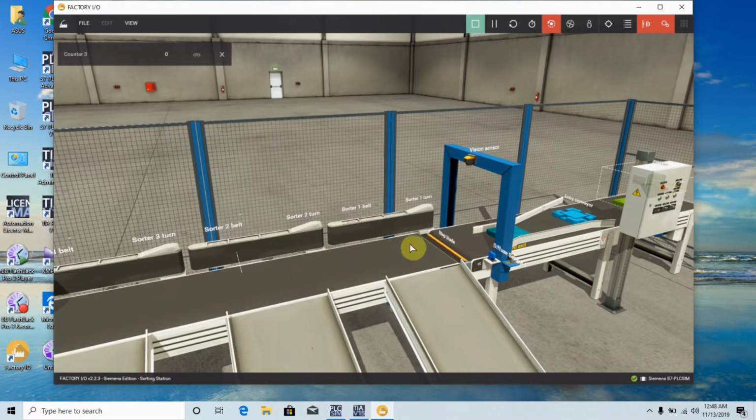And when this object goes through this sliding conveyor, there is a photosensor. When the object passes the photosensor, the photosensor also will give us a negative edge command signal, and using that signal I will reset this entry conveyor, and the entry conveyor will be started again, and also I will reset the sorter.